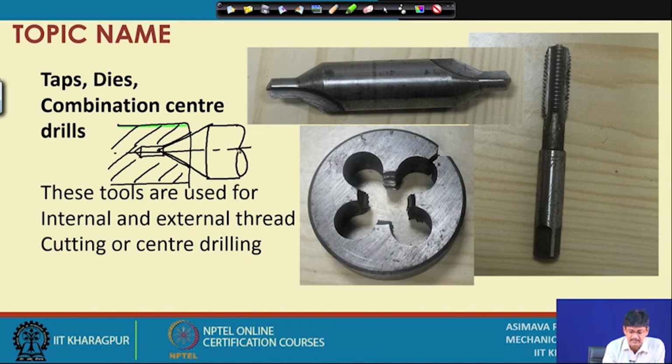I mean the axis of this center and the axis of the body which is being held will become aligned together. Moreover, since we are offering some latitude here, there can be some bending, so that when you are doing taper turning and other things, this will not be indenting at a particular corner. So, some latitude is there, and you can fill this up with lubricant, some sort of lubricating material, so that friction is less.